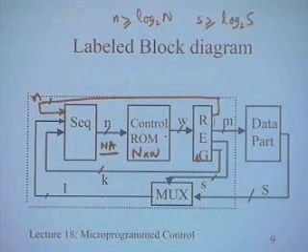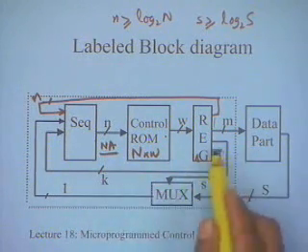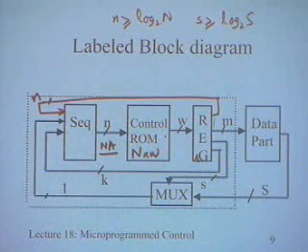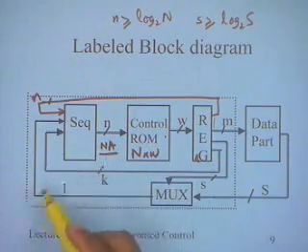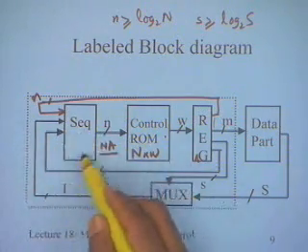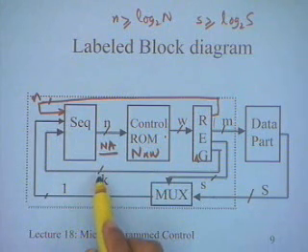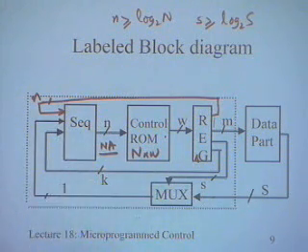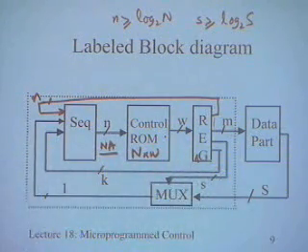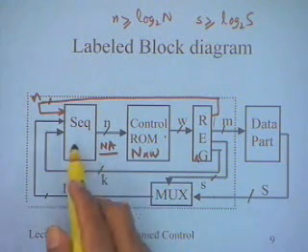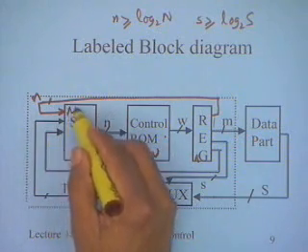So what sort of K is this, K coming from the register? K controls the sequencer action. It is sort of an instruction for the sequencer itself. The sequencer is capable of choosing between some of the options it has for generating the next address. The role of this K will become clearer again when we look at the design of the sequencer. For the present, you can assume that K is an input to the sequencer and defines the role of the sequencer in this clock cycle. The sequencer itself has certain capabilities. I am using the word sequencer as a microsequencer. I am not writing it here as microsequencer, but basically this is a microsequencer.